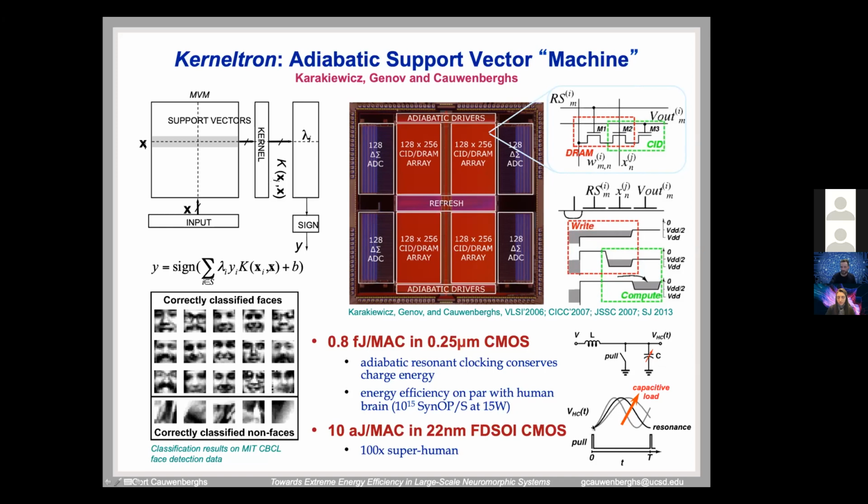So what we did here, rather than coupling with CMOS inverters, was couple with adiabatic energy recovery logic circuits, a bunch of switches that follow a hot clock. A hot clock is a voltage from a resonance in a tank, where you have an external coil that couples to all the capacitors in the array. At resonance, you get a transfer between magnetic energy and electrostatic energy, going back and forth, oscillating at this resonant frequency.